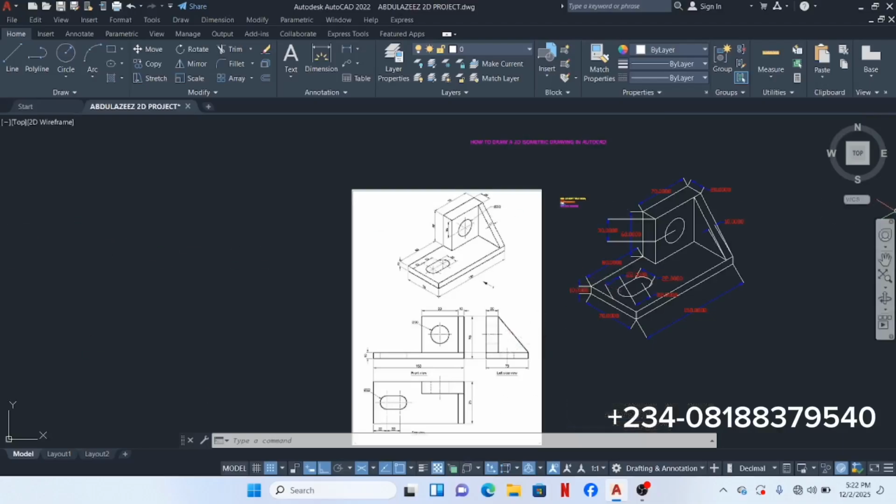Now I have the dimensions of all the lines. Now the dimension of the isocircles. Because it is an isocircle and AutoCAD sees the isocircle as an ellipse, a dimension diameter or dimension radius tool won't work directly.